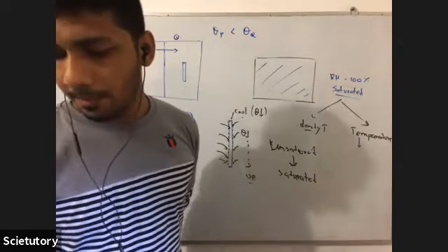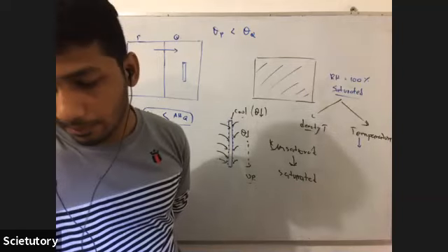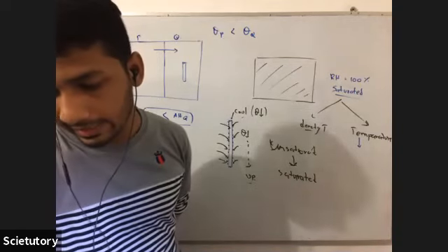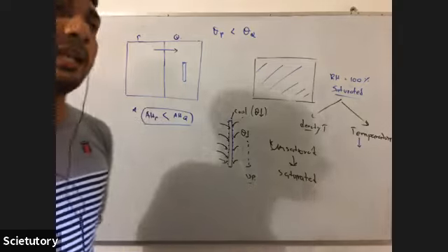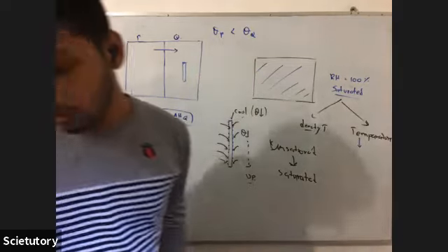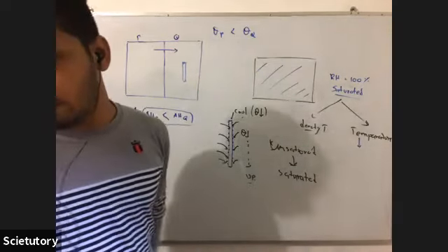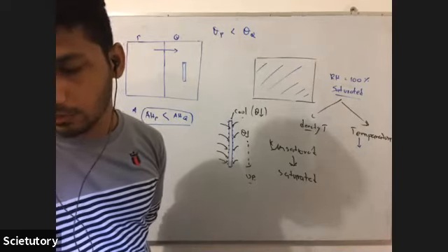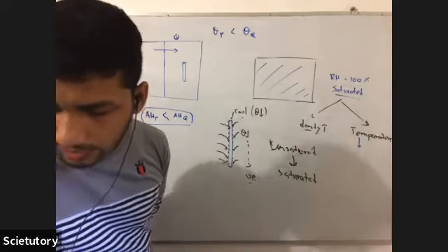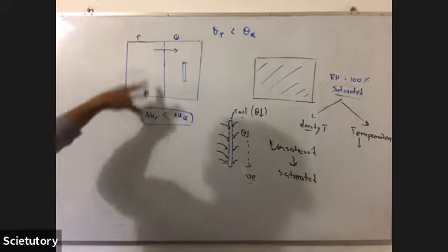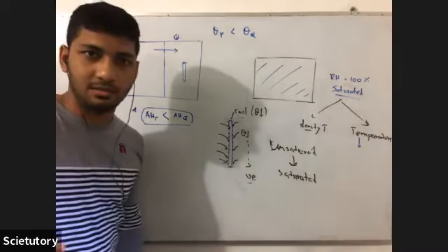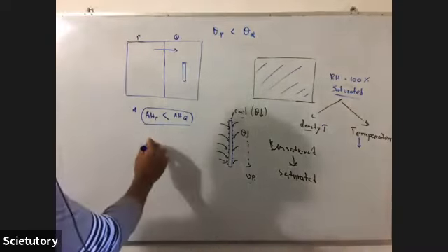So B, temperature of room Q is greater than the temperature of P. So that is correct. A is wrong, B is correct. And C, relative humidity of room P is greater than the relative humidity of room Q. So you can actually predict the AH of these two rooms, but not RH. Why? Because RH is expressed like this.